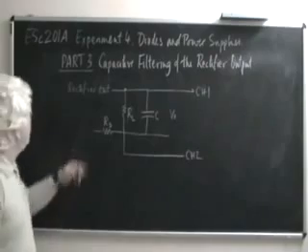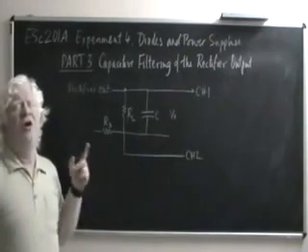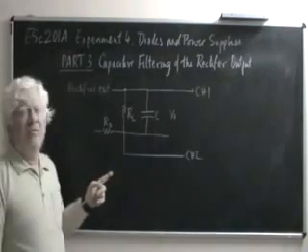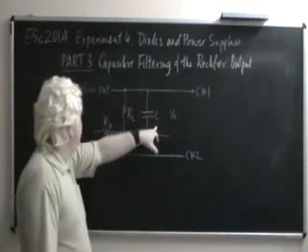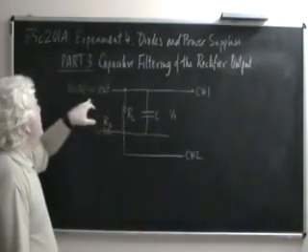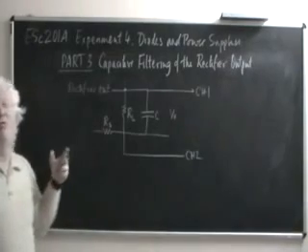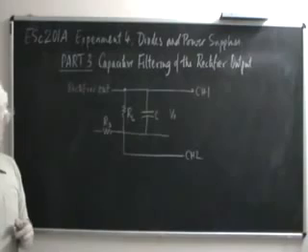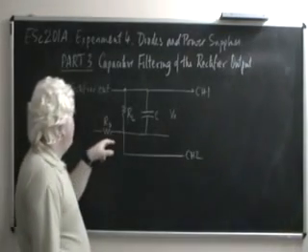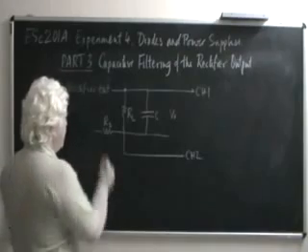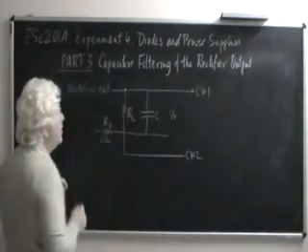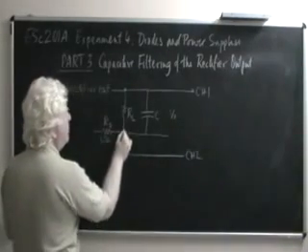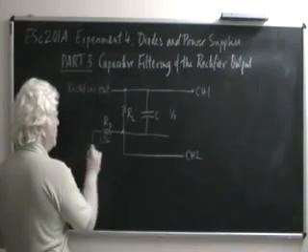This is the circuit you use to observe the waveforms of the output of a capacitively filtered rectifier. What you have here is the filtering capacitor and the load resistance. Here I have just said rectifier out. It could be a full wave rectifier or a half wave rectifier. Indeed, you have to carry out the experiment with both these. And we also include a small series resistor of 1 ohm on the ground side of the load resistance. That means to say, we don't ground this point as we were grounding earlier, but we ground this point.